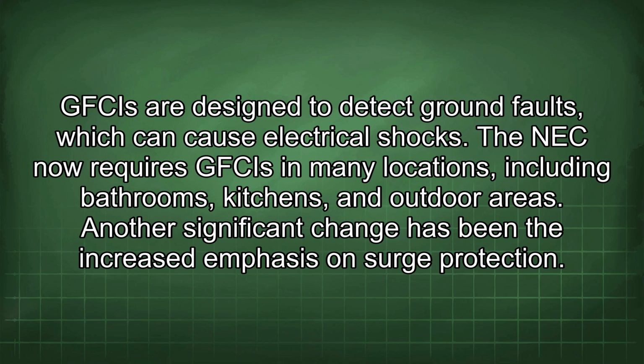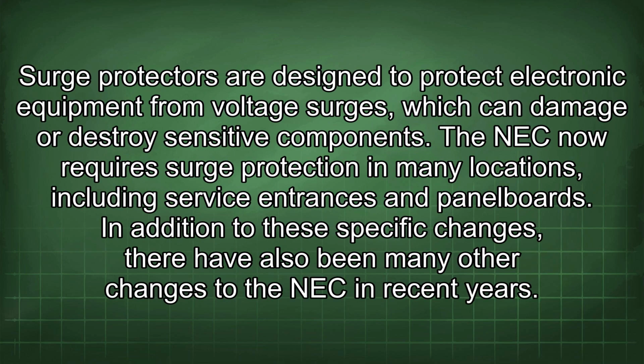Another significant change has been the increased emphasis on surge protection. Surge protectors are designed to protect electronic equipment from voltage surges, which can damage or destroy sensitive components. The NEC now requires surge protection in many locations, including service entrances and panelboards.